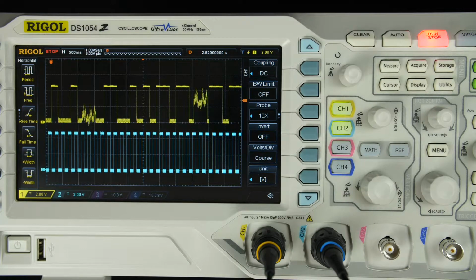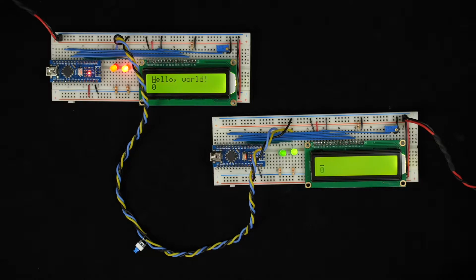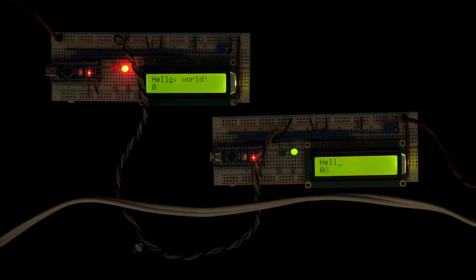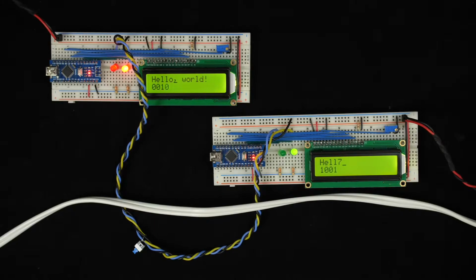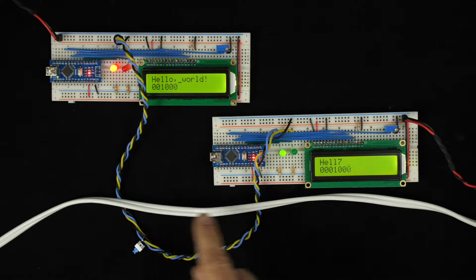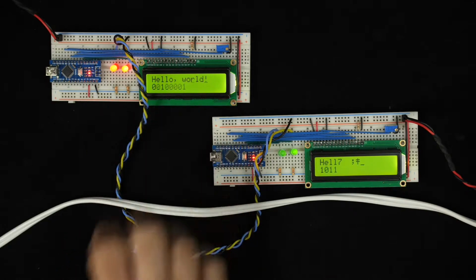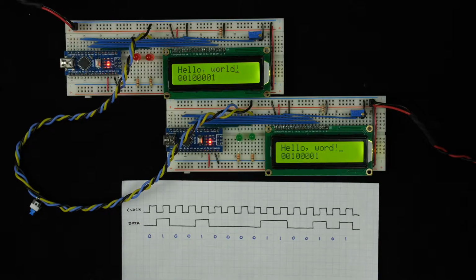Without a lot of extra engineering work, any circuit's going to be susceptible to some sort of electromagnetic interference. For example, if I run the power cord for my lights nearby the circuit, occasionally I can cause problems just by flicking the lights on and off. The quickly changing current in the power cord causes a changing magnetic field that might induce unwanted electrical currents in the nearby electronics. So, okay, if we accept that errors are going to happen, what can we do about it?